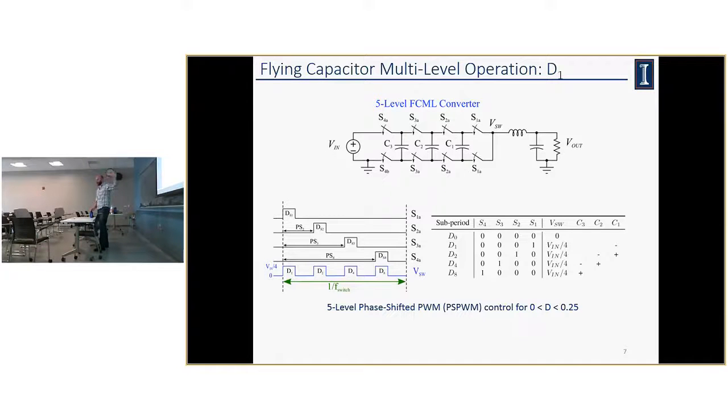The way we're able to just measure C3 here is because we're inducing an imbalance on that one. We know that there should be an imbalance on that one. We rely on natural balancing on the other 2, but we don't actually do any feedback or take that as an input. If you look at some of the results, the last capacitor does actually see a pretty decent additional voltage in the unbalanced case. But that's completely due to natural balancing not operating well in that case, as opposed to something we're inducing, because none of the auxiliary current is actually going through that one. Does that answer your question? Okay. All right. Thank you.